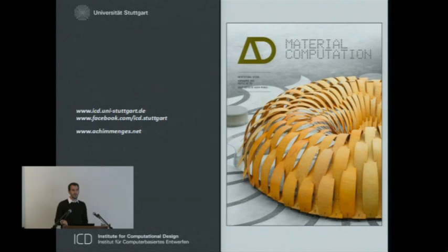On the other hand, the process is fairly robust in terms of the robot not making mistakes, because we scanned the scaffold, so the robot lays the fibers exactly where they physically are. For the next project, we're investigating having the robot scan the framework while it's working. So this is offline programmed: you program the robot to do what it should do before you run it. Obviously, in such a project, it's much smarter for the robot to know where the next point is and drive there by scanning the framework continuously, which is technologically very possible.